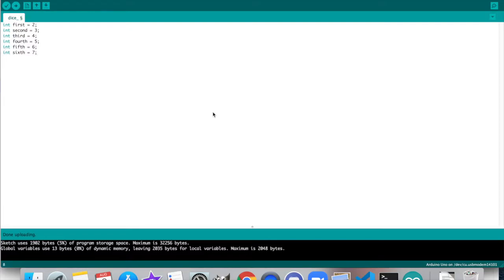and we'll also want to initialize our button switch pin, and a binary value to check the state of the button switch, since it only has 2 possible inputs. Int button to pin 12, and int pressed, which we'll leave at 0 for right now, which stands for false. Now we'll have the setup to do.